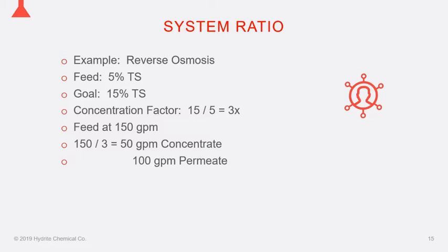Typically, your customer will have that, or the OEM will have that, or the membrane manufacturer will have the mass balance for that system. Because what goes in, the solids going in, will be divided into the permeate and the concentrate. So you have to be able to do that mass balance. But for this example, it's very simple, because the permeate is just water. There should be no solids in there. Everything else is captured in the retentate concentrate.